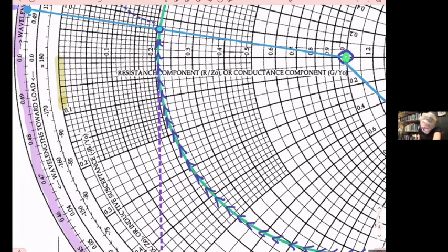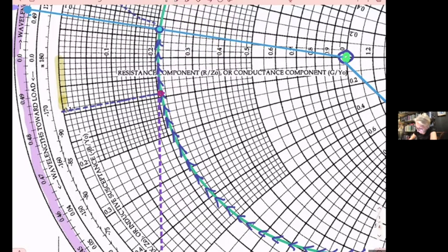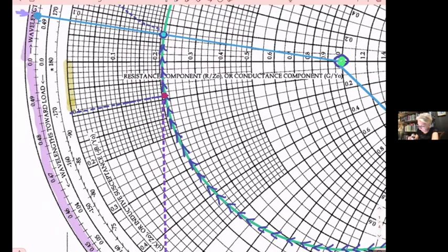So to be accurate, it will be somewhere here. And then I will go along this line, which is the constant reactance circle. They intersect all of them together somehow because they're so small. The point is right here. And that is going to be your Z sub T.